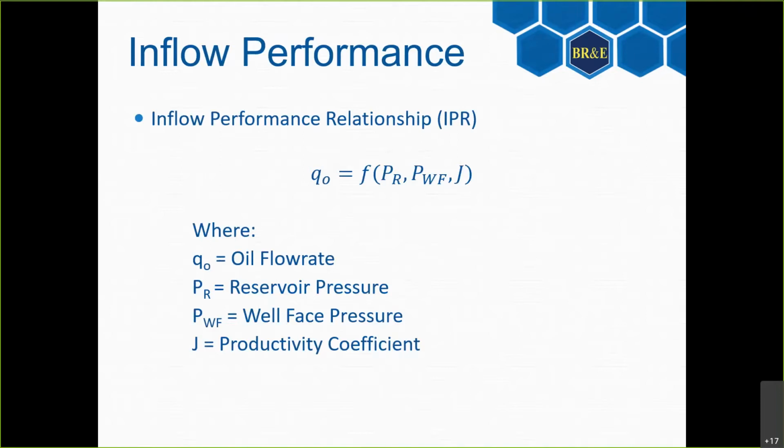And so the idea here is that we're going to use what's called a well test. A well test is, once again, we talked a bit about it before. Well tests are common for E&Ps to take. The idea is that we'll have to figure out, at one given set period of time, what the well face pressure was and what the flow rate was. Normally for a well test, like I said, if you have a lift pump, that might give you a live pressure reading, but if not, you'll have to shut the well in and figure out what that downhole pressure is, given the flow rate that you were flowing, and that will be considered a well test that you can use.